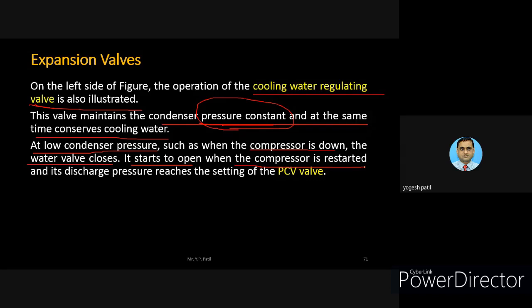When the compressor is started or running, then obviously the pressure inside the condenser increases and it is maintained constant after some time. To make that happen, that particular valve opens so that the water gets fed to the condenser and condensation happens there. And the discharge pressure reaches the setting value of the PCV valve. That valve is called the PCV valve. That is the cooling water regulating valve.